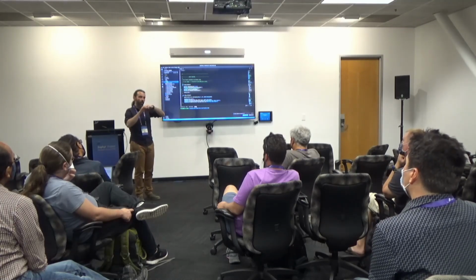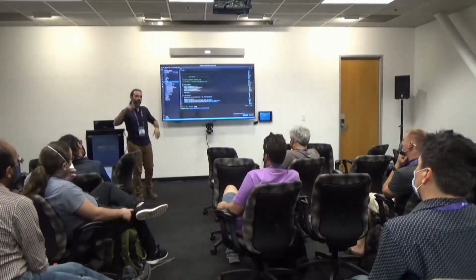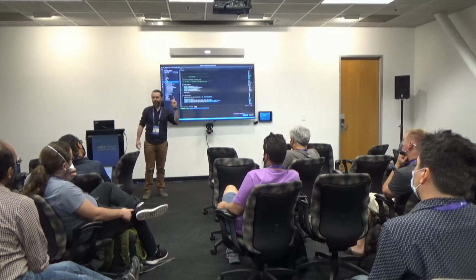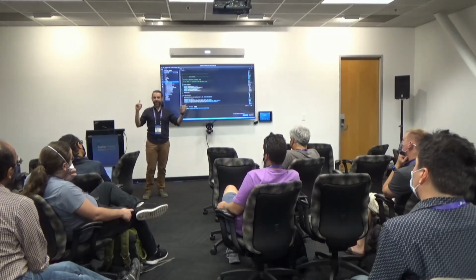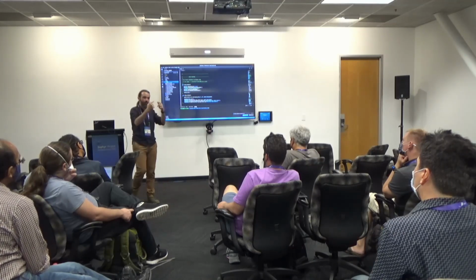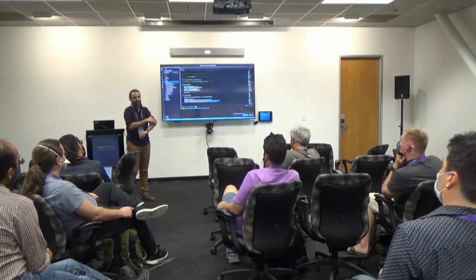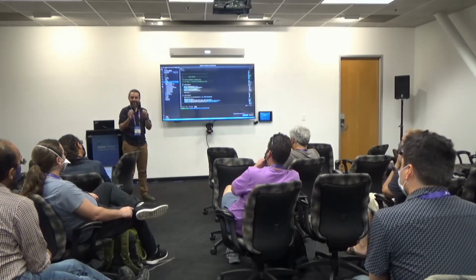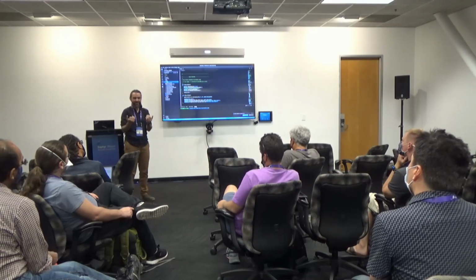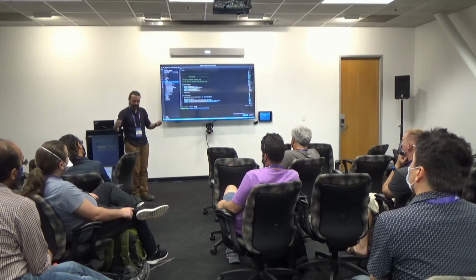You have to tell the ADC what its trigger is, and tell the HR timer who it is triggering, so we do it on both sides. That's transparent to the user. To be fair, it's an LL library from ST that we learned how to use, and we call a function that sets it up for us.